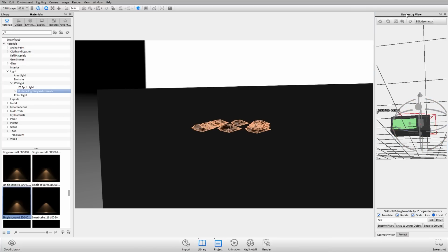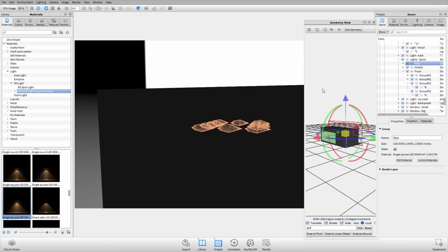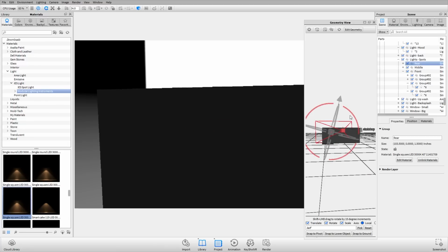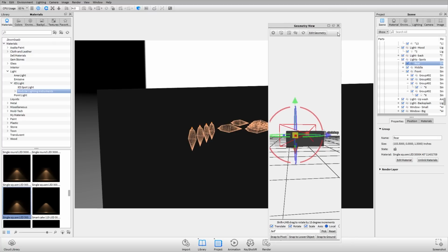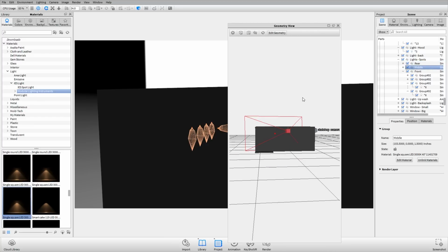Whoop, it keeps on docking. I actually don't want to dock it. But now you can see that if I rotate these lights and I hold down shift, they're now pointing in the right direction. So those are now pointing down. I'm going to expand this window a little bit, hit the little green checkbox. I'll select the middle, right click, move selection.